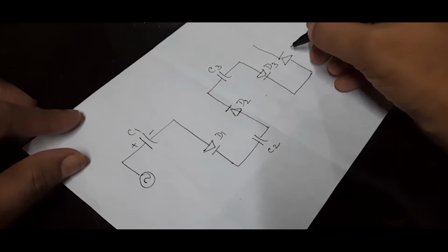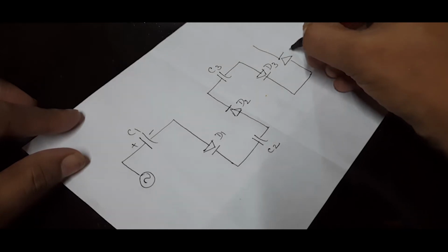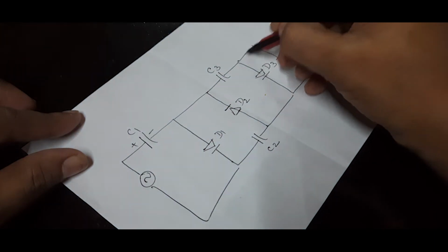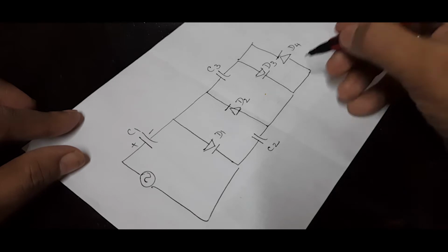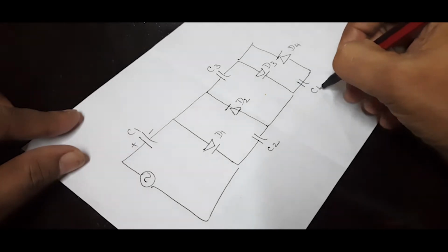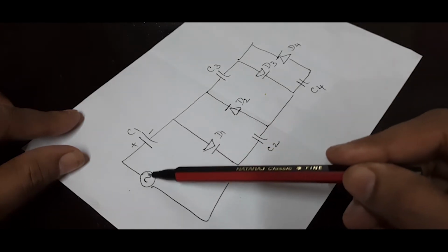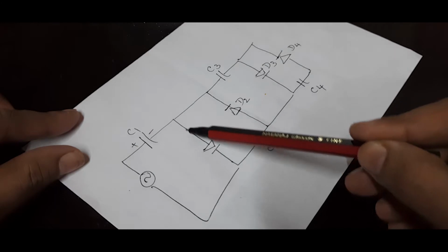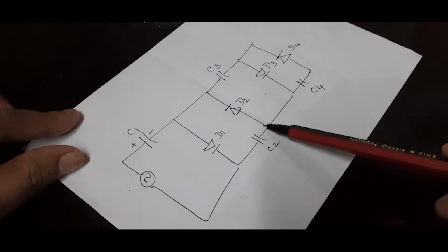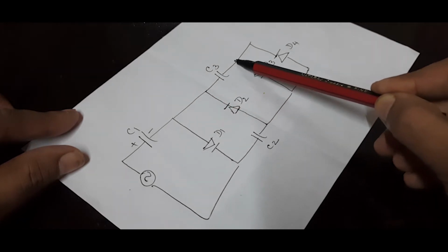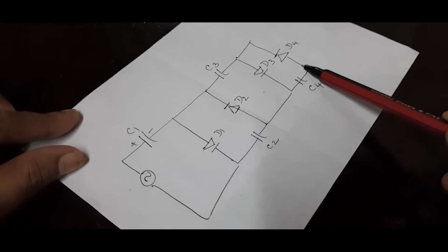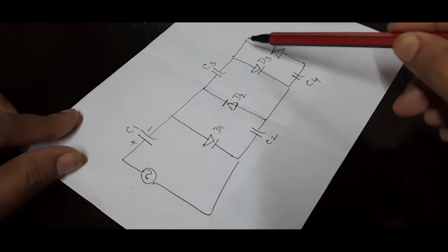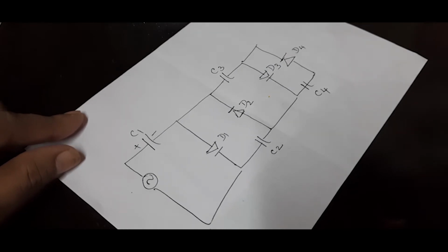So this is the framework of my voltage multiplier circuit, and I would like to complete the circuit with simple direct connections. So here I have left out the capacitor C4. So once again I'll follow the path for you. Signal generator or the signal, C1 capacitor positive, negative, diode positive, negative, capacitor positive, negative, diode positive, negative, and so on. You just need to complete it with direct connections to look like this. So this would be your simple voltage multiplier.